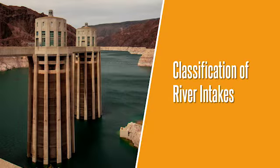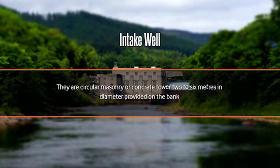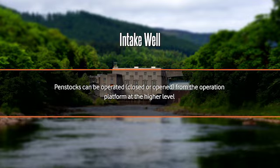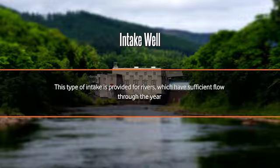Now the classification of river intakes. Intake well: they are circular masonry or concrete towers 2 to 6 meters in diameter provided on the bank. The water flows into the intake well through the penstocks located at different levels. Penstocks can be operated from the operation platform at the higher level. This type of intake is provided for rivers which have sufficient flow through the year.